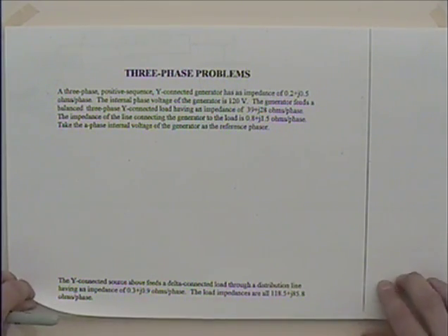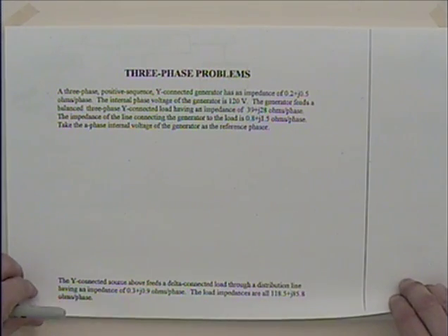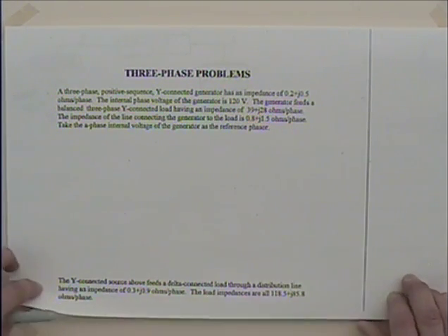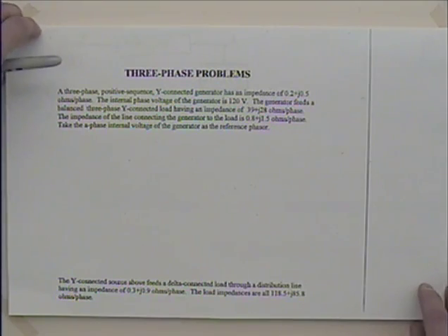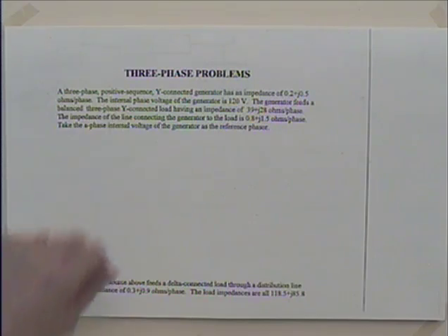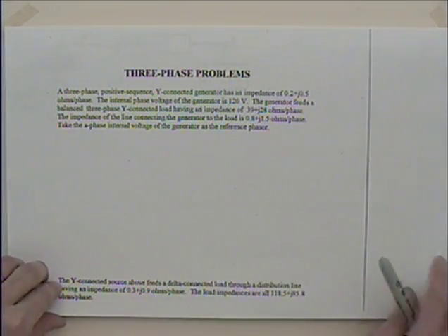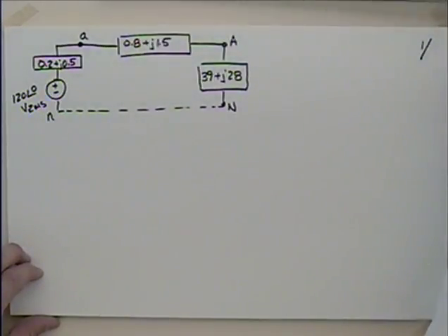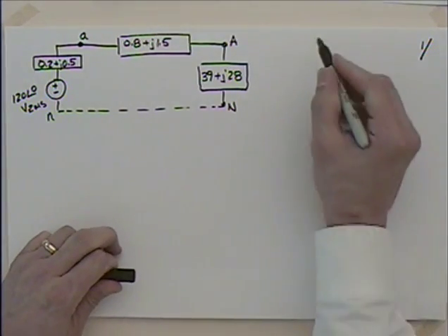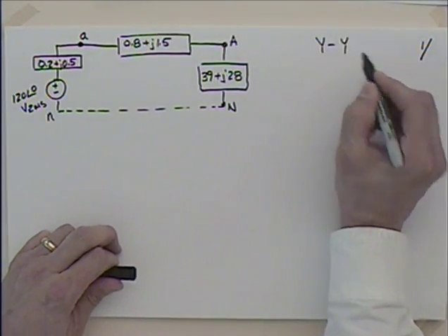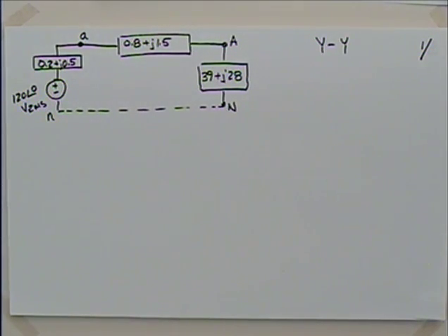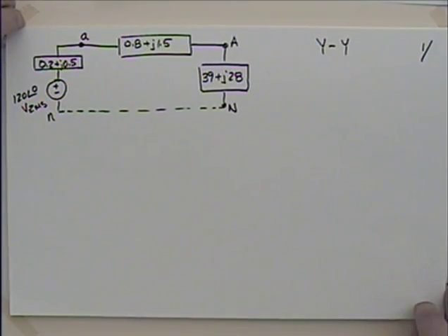And we'll get this set up and do a variety of calculations. I think we did that as we were finishing up last time. But I wanted to reiterate, most of these problems are in a verbiage form like this, and you've got to really read it for all its meaning. Positive phase sequence, this reference business. And when you go through this, you should probably build a single-phase equivalent circuit. Granted, we have a YY, and we don't want to forget that it's a YY. But there's no sense in making all three phases. We'll just make the A phase. You could do the B phase or C phase if you wanted to, but it's usually easier to do the A phase. And then we can just add and subtract 120 degrees on our answers.